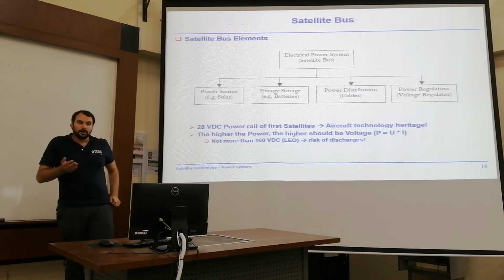Usually, when the satellite is placed on top of the rocket, you might have a connector that shorts the switch, and the moment the satellite is being deployed in space, it opens this micro switch, the PCDU starts providing power, and the satellite boots up. This is what you use this umbilical connector usually for.